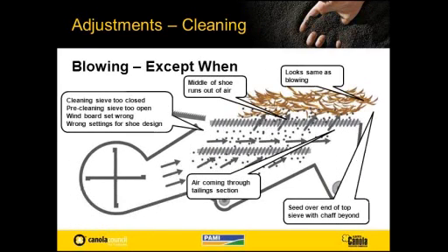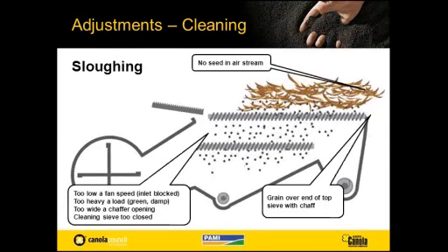Now there is a situation where you've actually got both things happening at once. It looks like it's blowing over, but it's really because you ran out of air somewhere on your chaffer halfway back and the material sat down. So it's actually sloughing all the way to the end, and then usually maybe an air blast from the tailing section is a little higher and lifts it out, and it looks like blowing. So that one is a lot harder to identify, but it can happen.